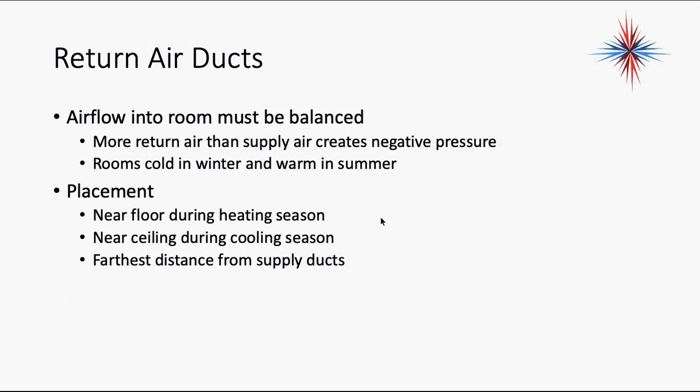If I have a negative pressure in a room, unless you're in a hospital area where you have to create negative pressures in certain areas, it's a very bad thing, because you'll hold your hand against outside outlets, you'll hold your hand against windowsills, and you'll feel the air being pulled into the environment. So again, negative pressure in a room is a really bad thing.